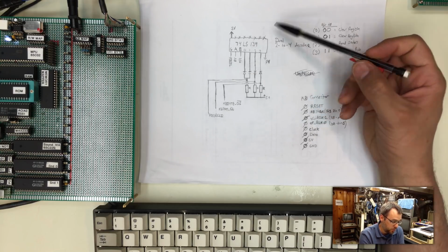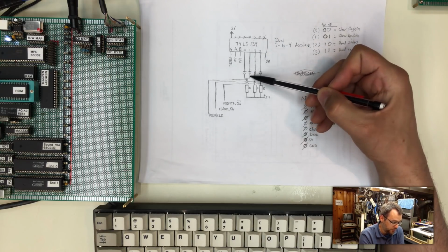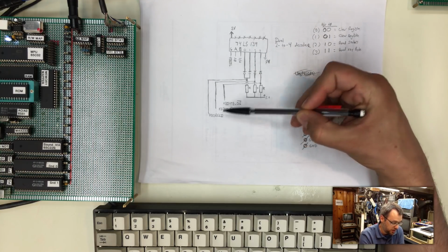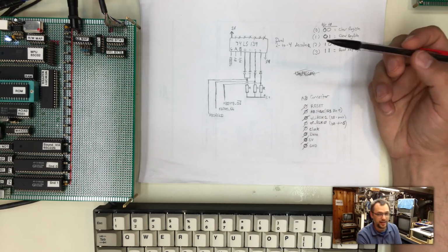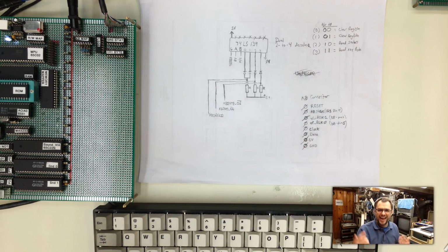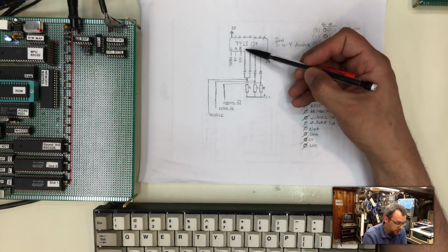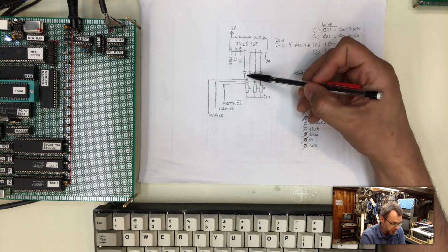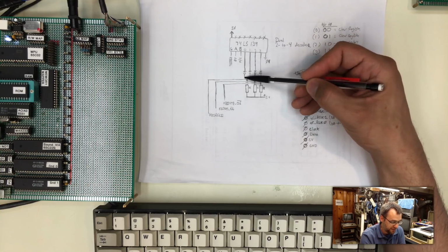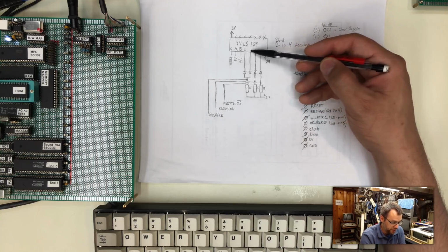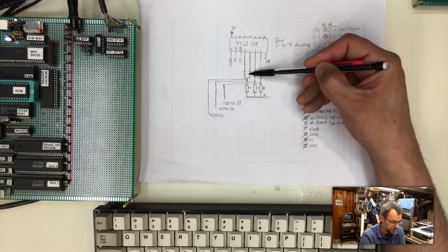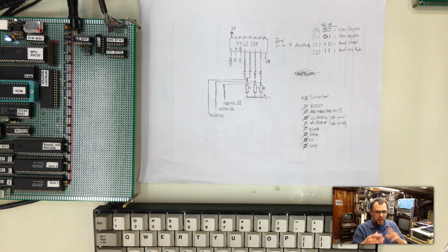Here it is going to be required because we have two outputs coming together, so that either one of these is going to select that SR clear. And again, this effectively acts like, is it an OR or an AND? It acts as a logic circuit, so that if either one of these goes low, the whole thing will go low. The diodes help prevent backflow out of these when they're high, out onto the circuit, and this is what's providing the high level instead of these two. Does that make sense? I'm going to go over that again because it barely makes sense to me.